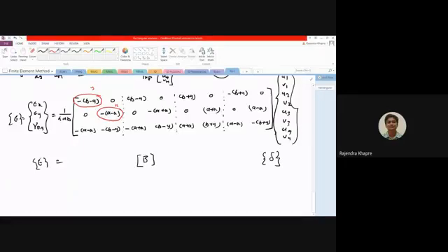This will be very useful for us when we want a variation of stresses or strain within the element. In CST it was constant. Here in this case it is not constant at all. So for example, if you know these values, that is u1 v1 u2 v2, they are known to you. Let me take a simple example. Let me draw a simple box. Now you know the deformations happening in this particular box. Let us say the deformed shape of this box is something like this. This means you know the deformations and it is going to deform like this.